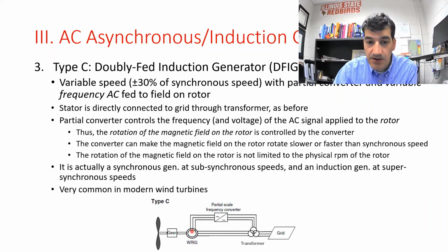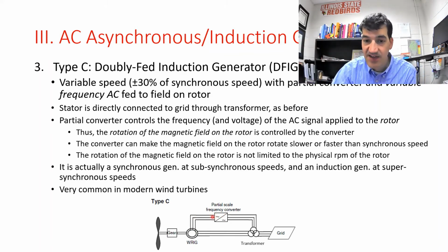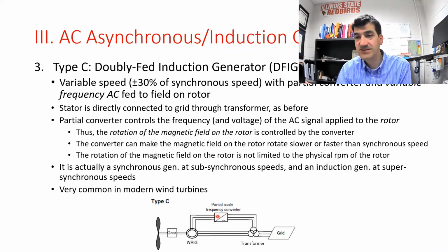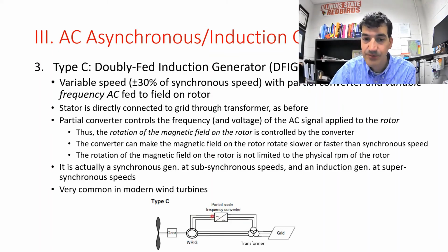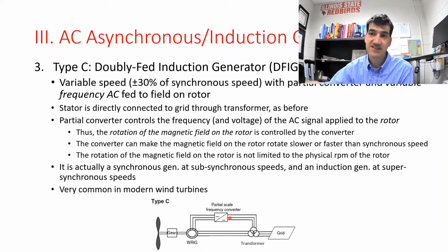That comes out of the rotor windings through the slip rings and the brushes, and then goes back into the converter the other way. The converter can take that, we don't know what variable frequency it's at coming off of the rotor, and it turns that into DC and then back into nice, clean 60 Hertz AC and applies that back to the electric grid.